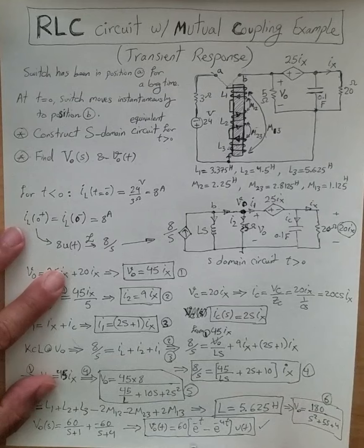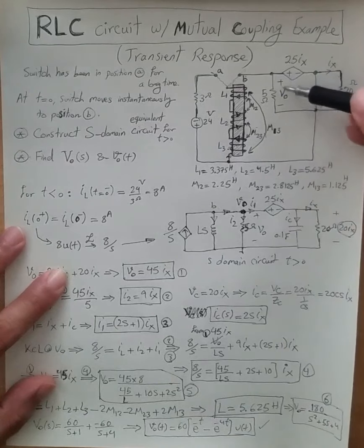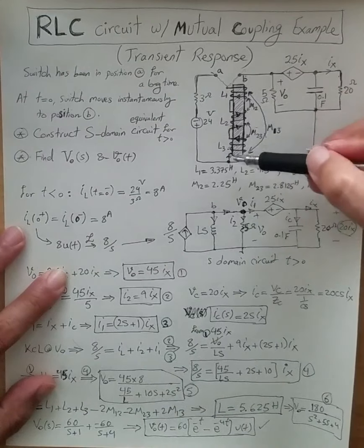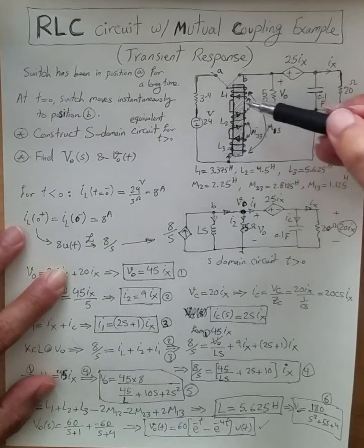And this is in line with our expectation, because at time t equal to 0, you can see that it becomes 1 minus 1, so Vout at time 0 should be 0. And that is exactly what we expect, because Vout is the voltage across the inductor, which at transition time should be 0.